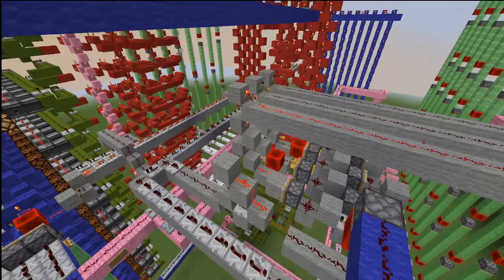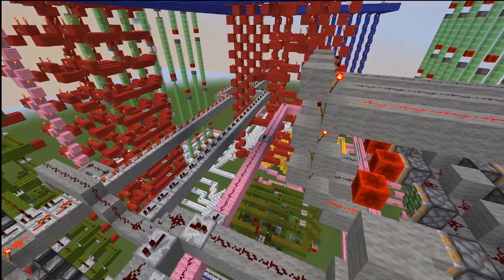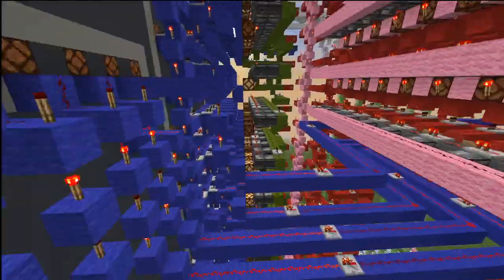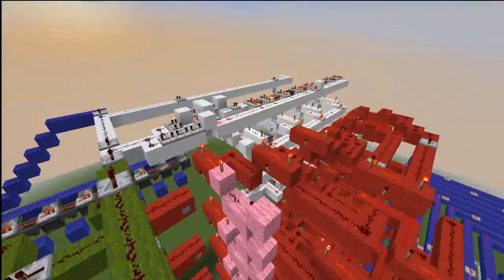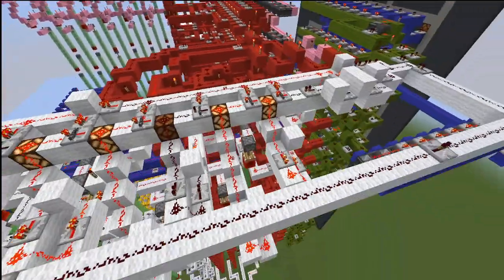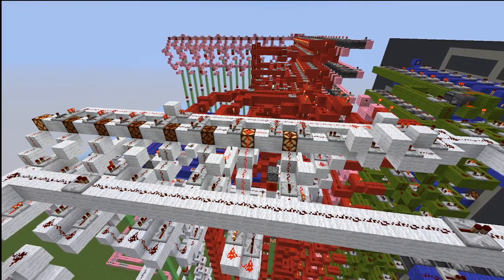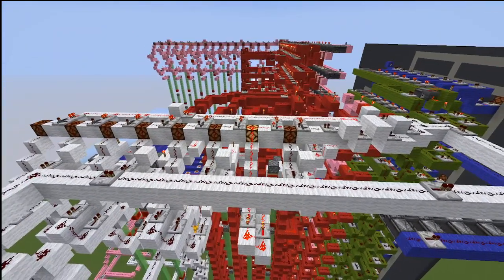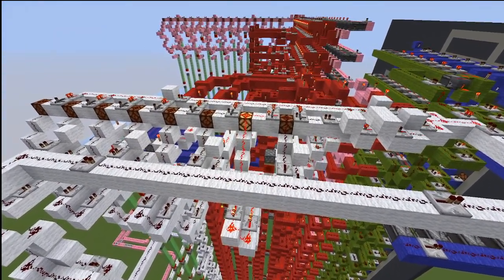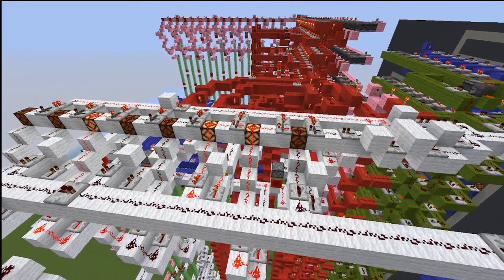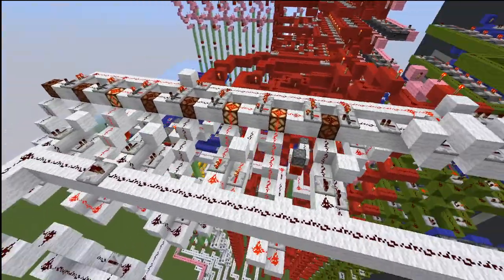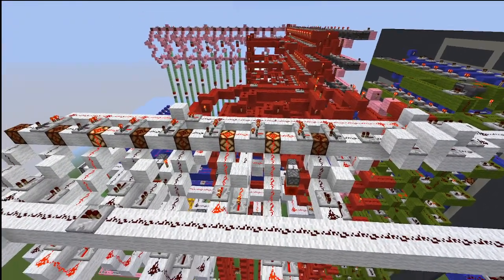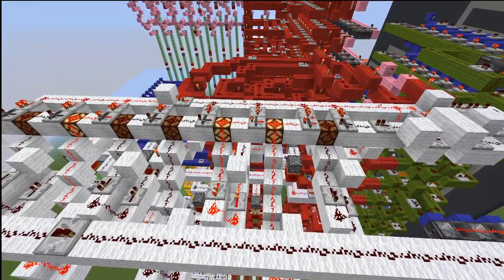Anyways, it's about to hit this next clock pulse, which means the add macro instruction will start. So here comes the clock. It just updated the clock. So if I come to the address and data bus here, it's going to read from the program counter, which should give a 2, and there it is. And then it's going to read address line 2 out of the prom and put that into the address and data bus here, which it did. And now it's going to write that to the instruction register like it did before. And then it's going to increment the program counter. So the program counter will have 3.